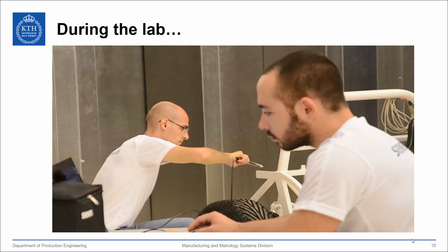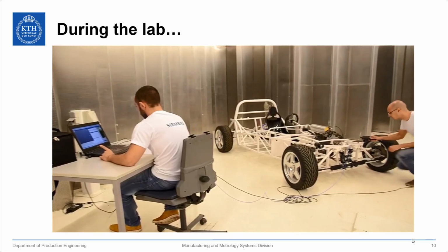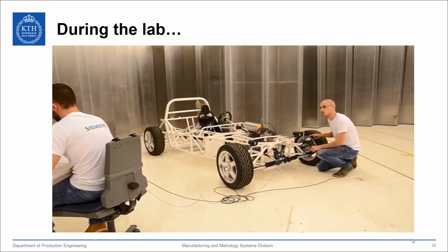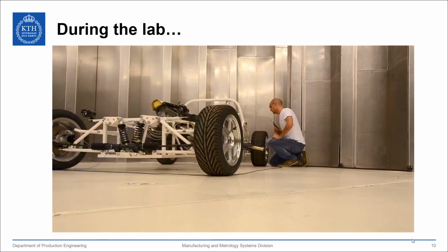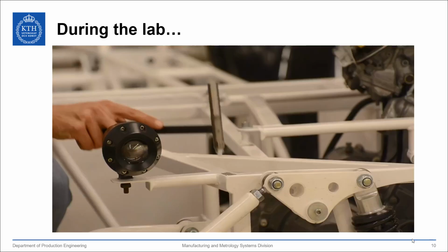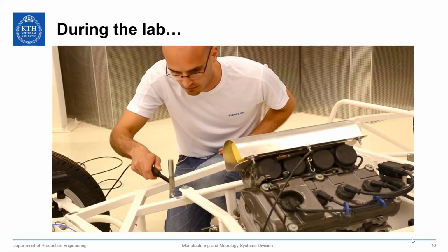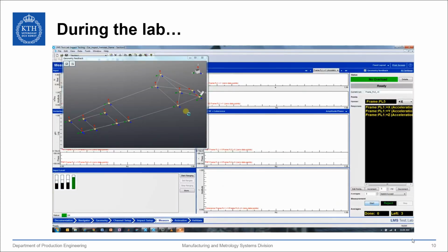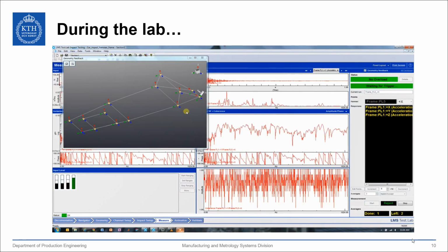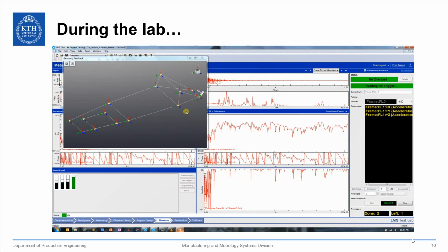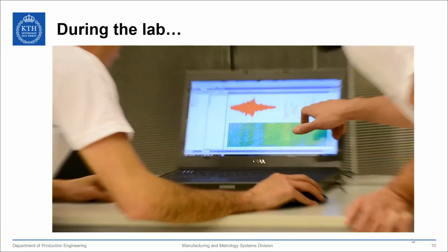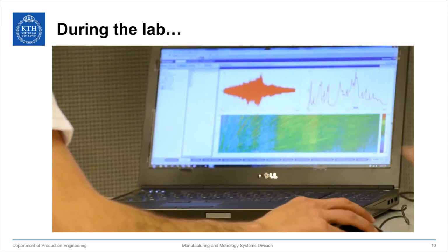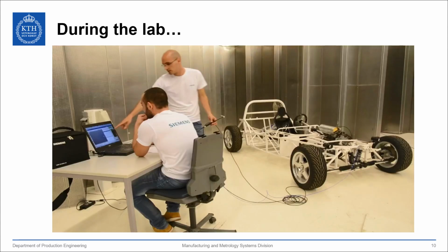You can now start measuring by hitting the impact hammer onto your system's surface. It will take the setup an average of 3 hits to produce a first set of frequency response functions. Comparing these functions to the occurrence of vibrations during system operation will help you pinpoint the origins of your problem.